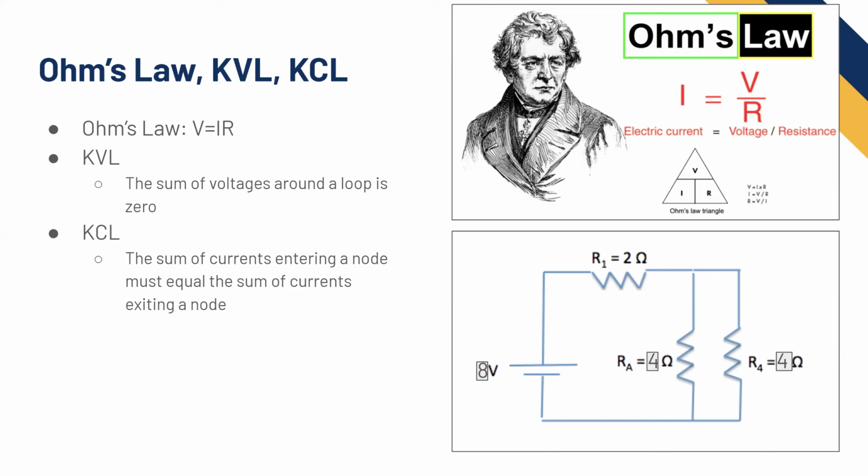Or, if we had never figured out the current, we can use the voltage divider equation, which I'm not going to derive here. The voltage divider is basically if you had a voltage input and then a resistor on the top, and assume the two parallel resistors are one, you can say the voltage at the top right node is going to be the vertical resistor divided by the sum of the resistances times the input.